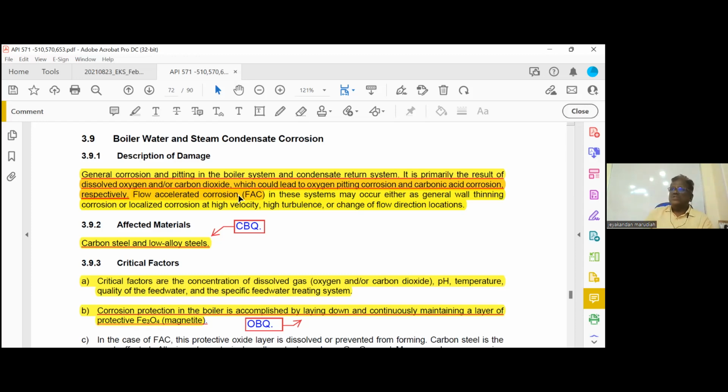Then what will you do with the steam? There are two problems. If you leave the steam like that, it will pollute the area. It will raise the temperature of the area. Second one is, we can reuse the steam because the steam is generated from not potable water. It is from the boiler feed water, especially treated water. So they will use a condenser to condense the steam back to water. So there will be a vacuum pulling. They will condense the steam into water in the condenser.